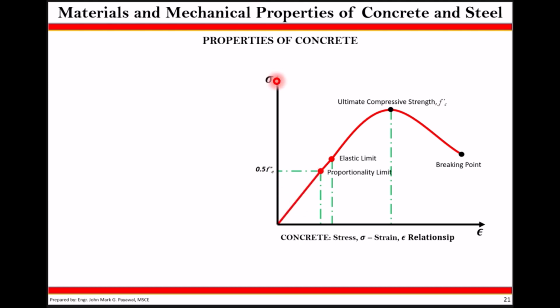An increase in your stress would be directly, or linearly, proportional to the increase or decrease in your strain. This is again a linear or elastic relationship. However, after the 0.5, your concrete now behaves in an inelastic or non-linear manner. This is important to know because as we proceed to a more advanced discussion of properties and materials, there will be instances where your concrete is behaving linearly or non-linearly.